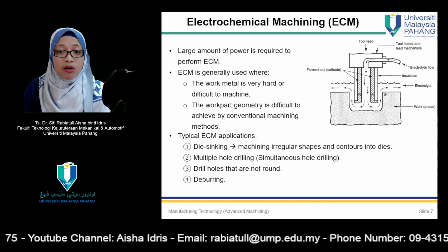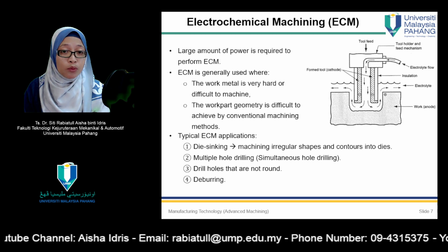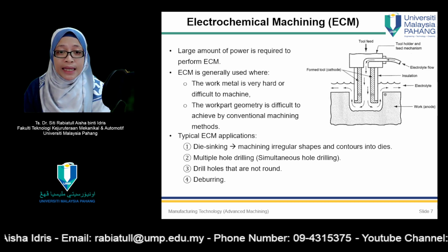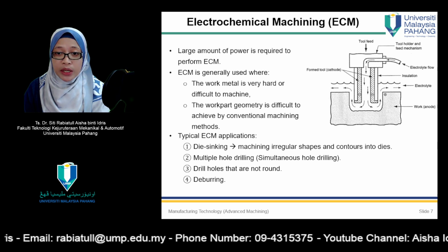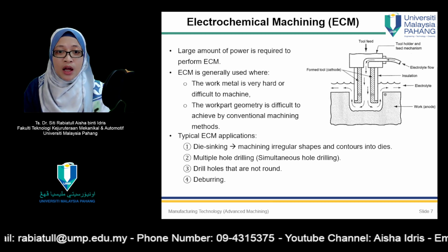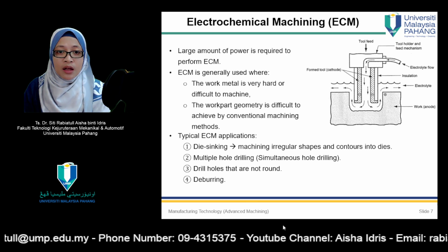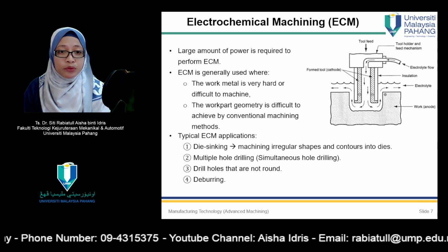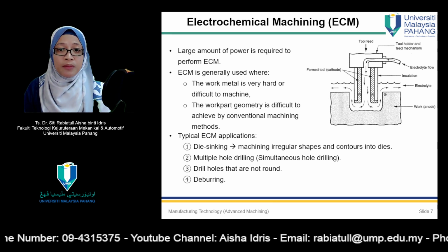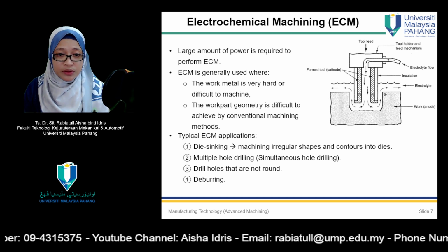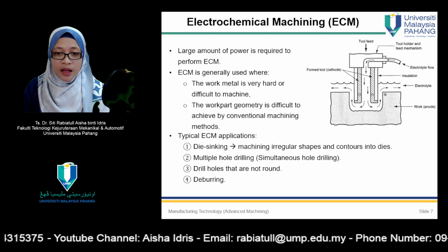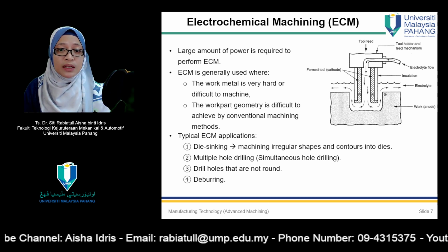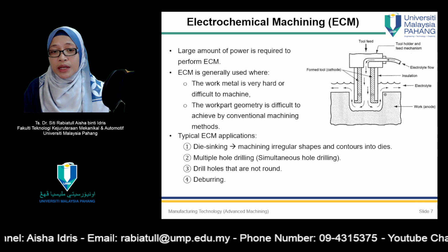In addition to carrying off the material that has been removed from the workpiece, the flowing electrolyte also serves the function of removing heat and hydrogen bubbles created in the chemical reactions of the process. The removed work material is in the form of microscopic particles that must be separated from the electrolyte through centrifuge, sedimentation, or other means. The separated particles form a thick sludge whose disposal is an environmental problem associated with ECM.